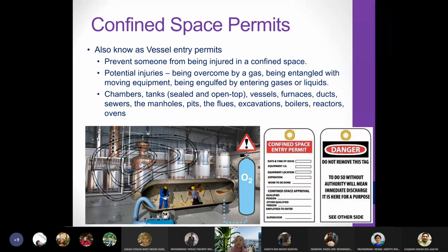So this is also known as the vessel entry permit. The vessel entry permit, or a confined space permit, prevents somebody from being injured in a confined space. It's because you can get suffocated in a confined space if there's not enough oxygen. There are a lot of potential injuries in a confined space.